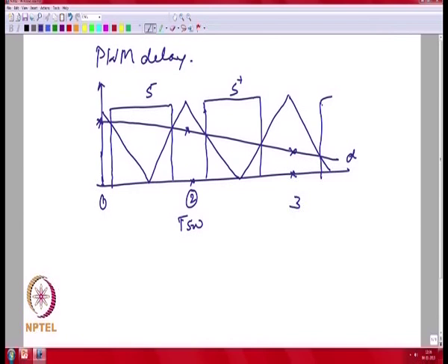But you can see that in the case when your duty cycle is close to 1, an update over here will give you a fast response for the operation. Your output voltage goes up to a high value very close to when your actual computation is updated, whereas if you look at point 3, you are updating over here, and now you have a delay between when your actual switching action is taking place and when the computation is being provided from your controller.